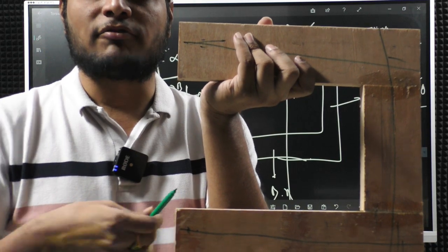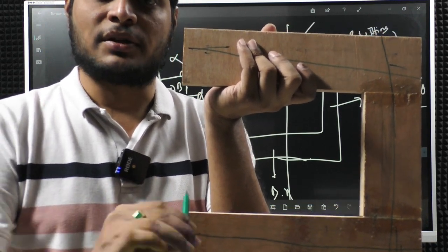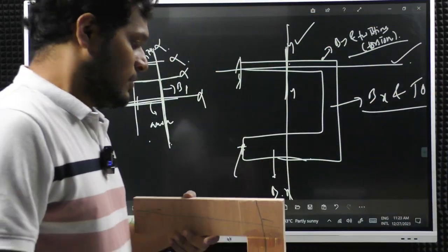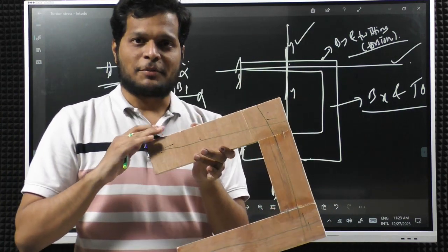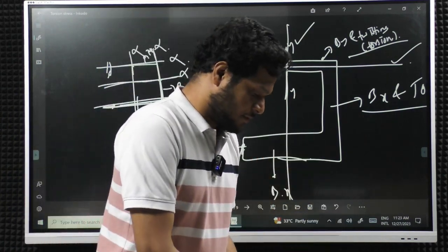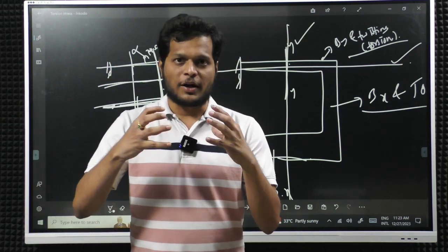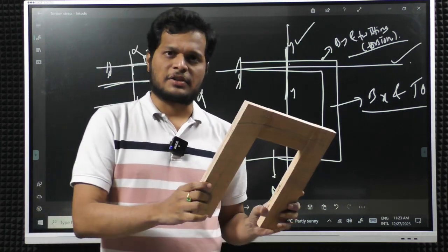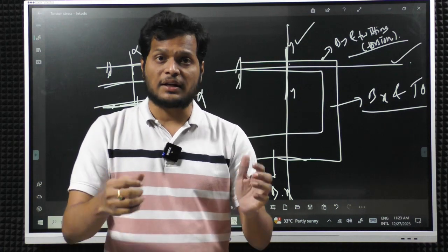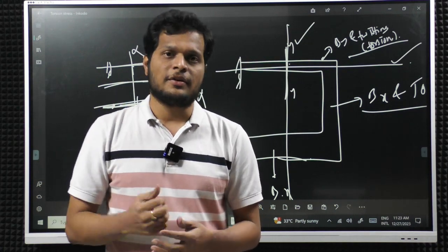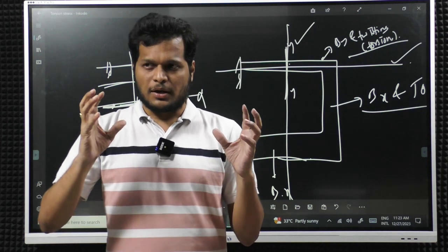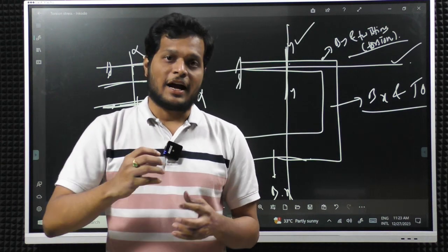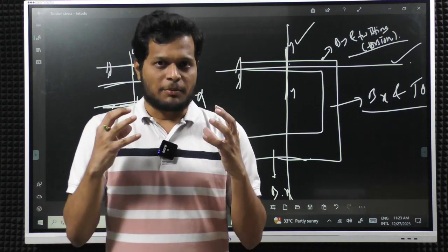If you apply a load out of the plane, then there will be torsion in these two. Here also, if you apply away from the center, then three beams will be in torsion. Okay. So this is how. So just to make you feel, I prepared this shape. Okay. So I hope now you are able to feel the torsion exactly. Even when you prepare a shape like this with any plastic body which will deform easily, you can really see the twist also. Okay. So if possible, in further classes with some sponges or foam which generally bends easily, or with plastic, if I am able to make such shapes, I will try to show the twist also to give you a better feel. Okay.